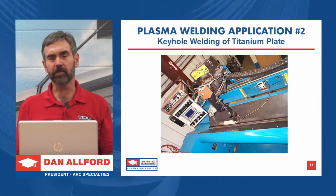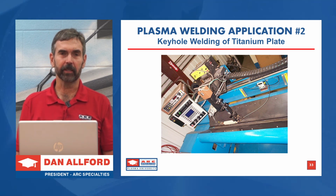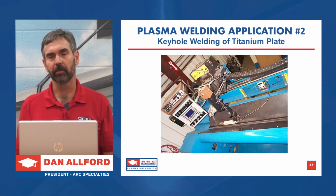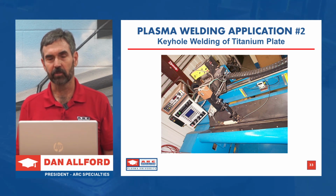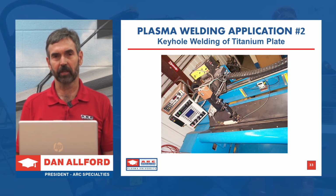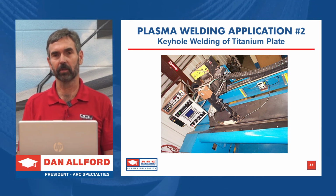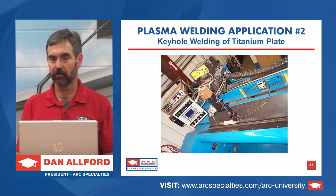Keyhole welding. This is another unique thing about plasma. As you're familiar with, plasma cutting is commonly used in industry. And the only difference between plasma cutting and welding is gas velocity. So if you were to turn up that plasma gas flow rate to a point, it will actually cut, and so you've created a cutting torch. Well, we've capitalized on this phenomenon by controlling that plasma gas flow rate while we're making square butt welds. So keyhole welding allows you to weld square butts up to, I would say, 5/16, maybe 3/8 of an inch thick without any bevel at all.